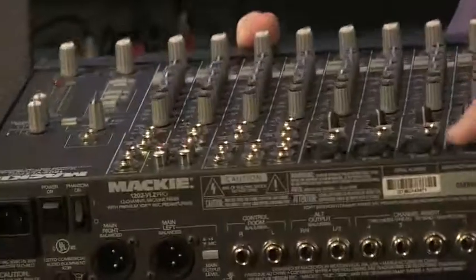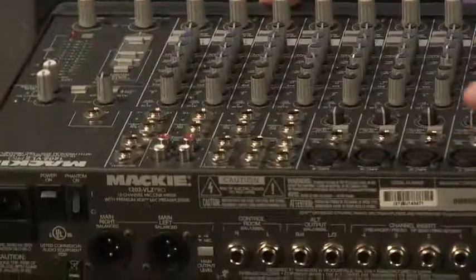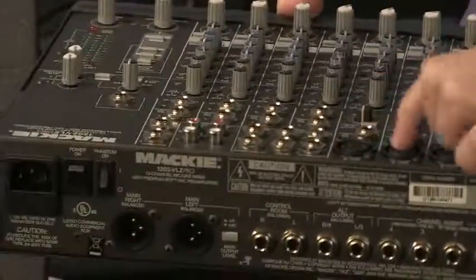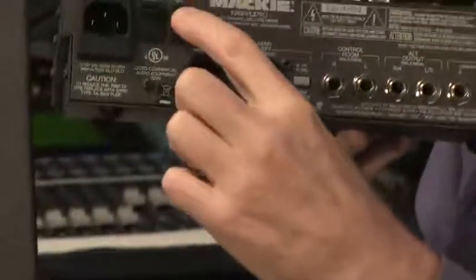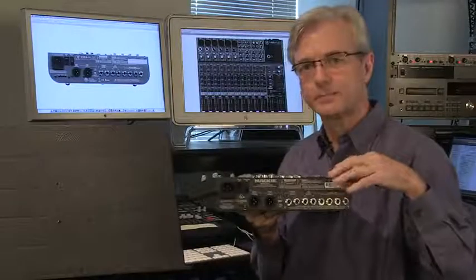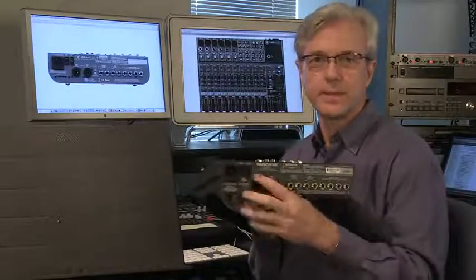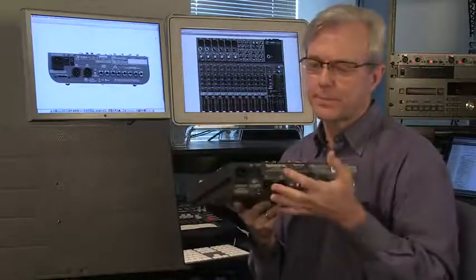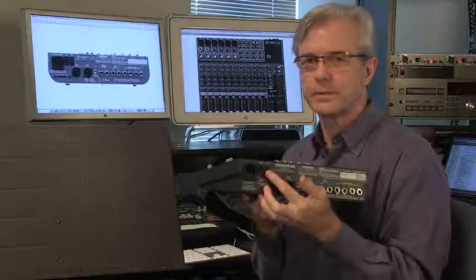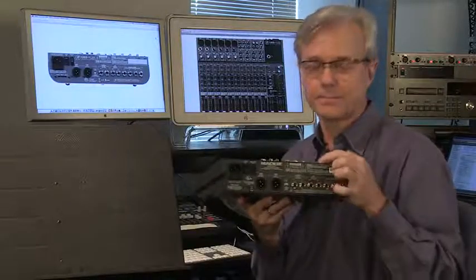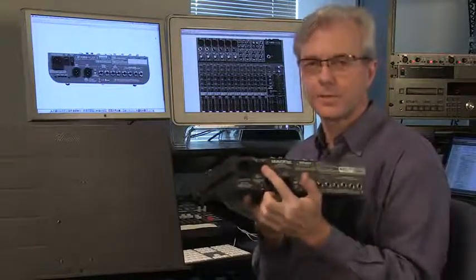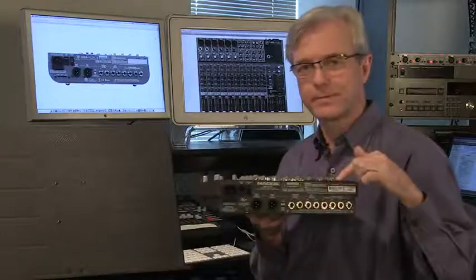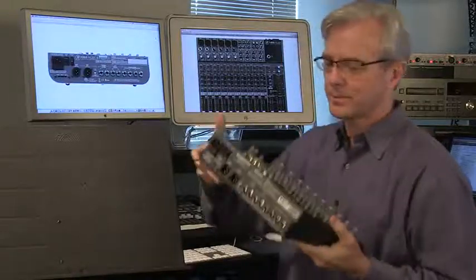The phantom power only goes through these first 4 channels of inputs in case you have a condenser microphone that needs to be charged up. If you're using a dynamic microphone, then you would not need to turn that on. It's not going to damage the dynamic microphone, it really just ignores that information. But there could be some situations where it could potentially damage certain kinds of devices. So I would always recommend turning off the phantom power if you don't have condenser microphones plugged into the inputs.